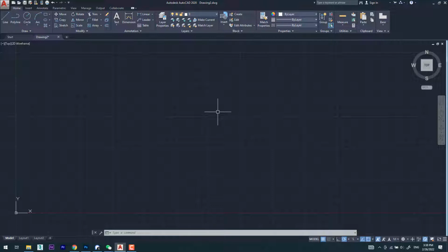It means that it is not in between doing anything. It's not in between any command, not in between any process. So if you have to start anything, you have to make sure the cursor is neutral. And how do you make sure? You press escape and your cursor is neutral.